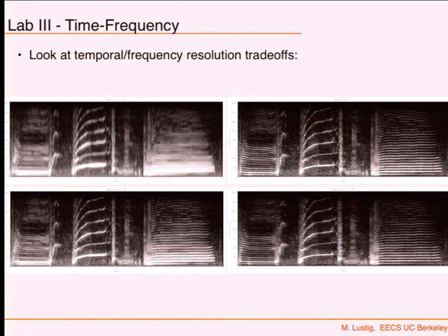By the way, that's why multi-rate processing is also important. If you're going to take only 200 kilohertz out of this 2.4 megahertz, absolutely you can reduce the computation significantly by doing operations like downsampling, filtering, things like that.